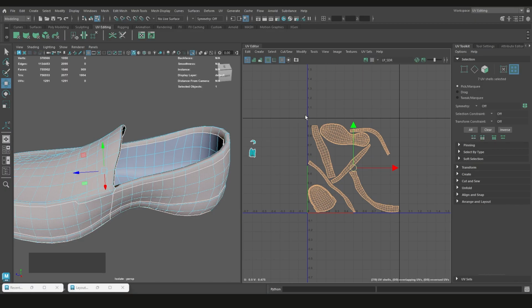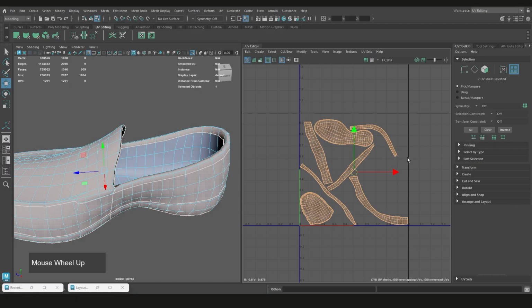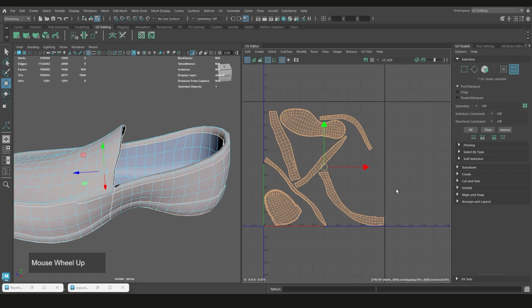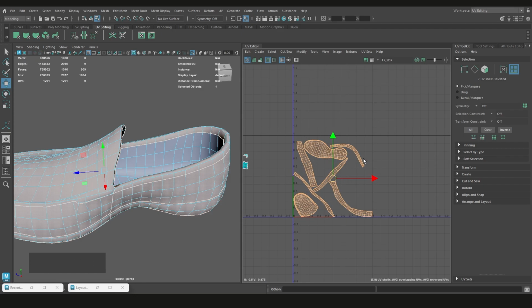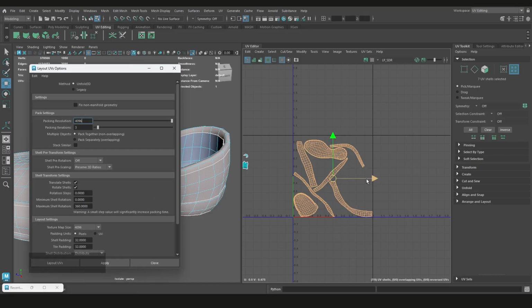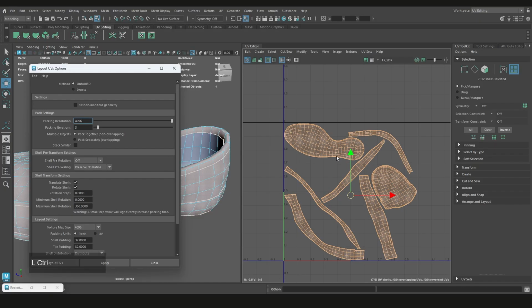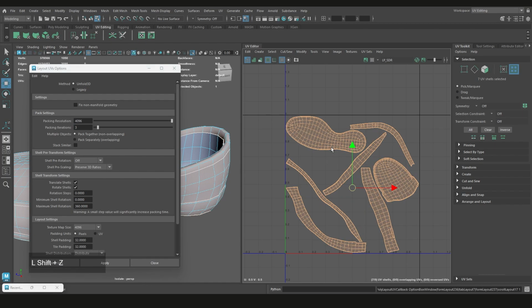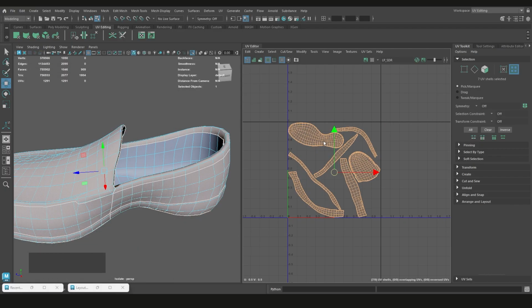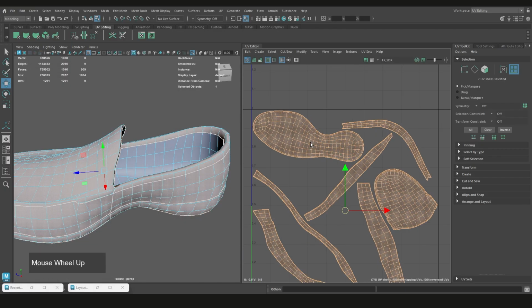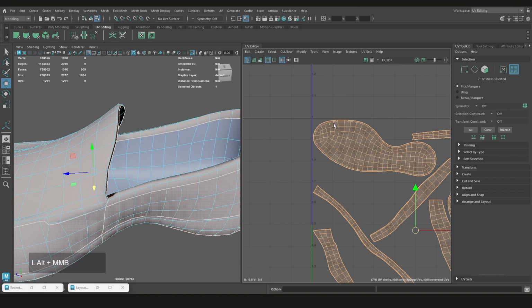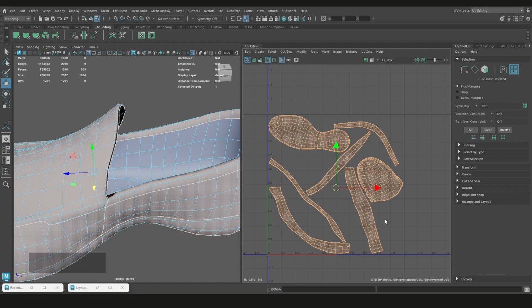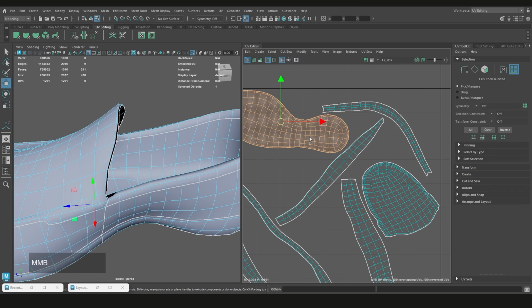So this here is your UV space. I hadn't explained this, your UV space. You want to use as much of this as you possibly can without overlapping the edges. And if we do this, right, and we go to layout and layout UV, apply that. You notice that these pieces got just a little bit bigger here, right? If you look at that, you're just a little bit more, right? And we want to optimize this to take up as much space as it possibly can without it having to overlap these edges here, right? So one and one, and without having to overlap each other like that.